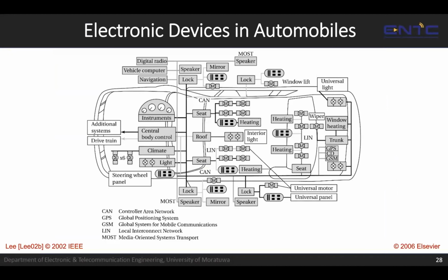Now, these kinds of microcontrollers are everywhere. If you take a car, for example, it is going to be a very complex system, and it's not just one embedded system. So now you know that if you don't close the door, an indicator comes up. That is actually one system, that small functionality that has a sensor in the door to check whether it's closed or not, and then it communicates with the vehicle control unit, and then it has to go to the dashboard, to the indicators, then it comes up. So an automobile is actually a combination of embedded systems, because if we go with this complexity, it is very hard for us to understand.